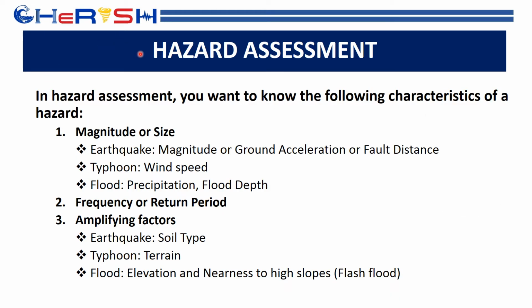Hazard assessment. In hazard assessment, you want to know the following characteristics. The magnitude or size of the hazard. For an earthquake, it may be ground acceleration, it may be fault distance. For typhoon, it might be the wind speed. For flood, it may be the flood depth. The frequency or return period used in the assessment is important.